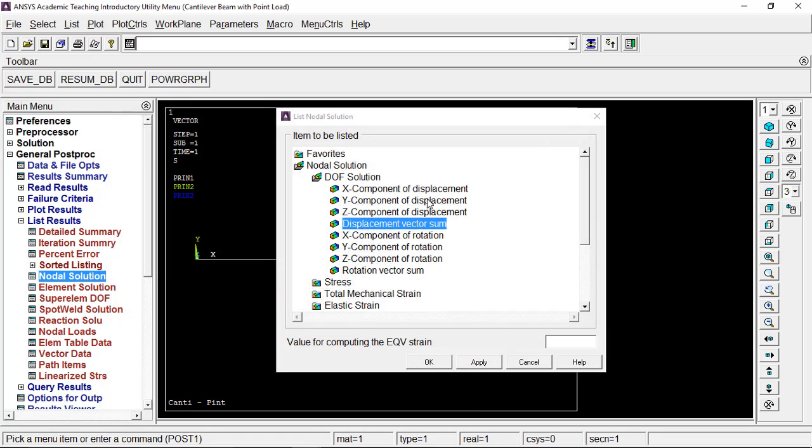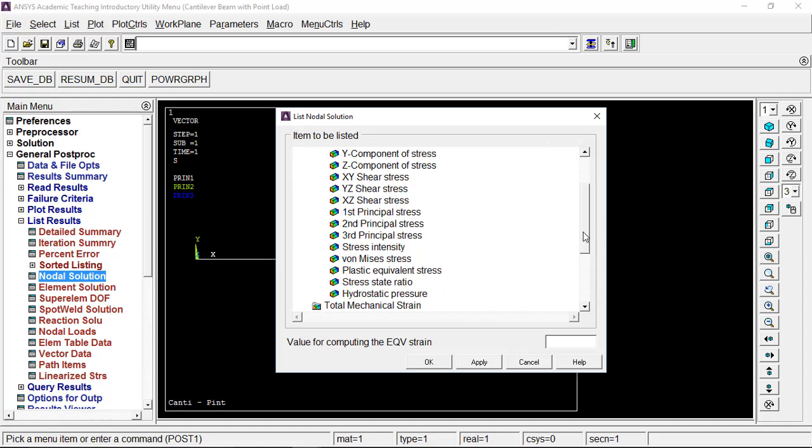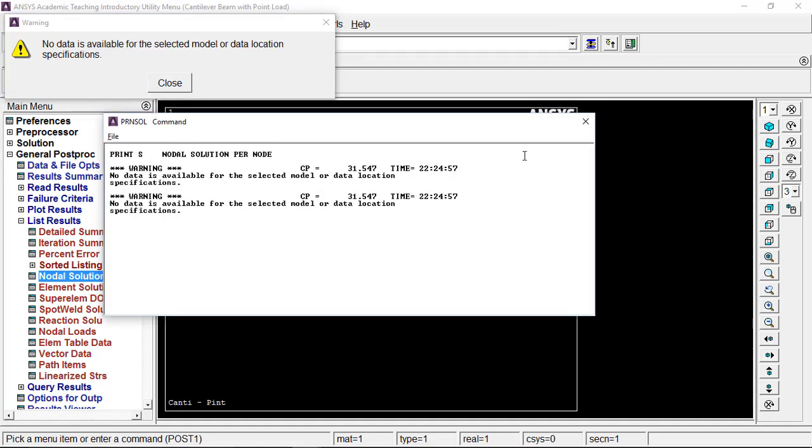And then next, if you want to see the stress, go to stress and then go to von Mises stress and then give OK. Sorry.